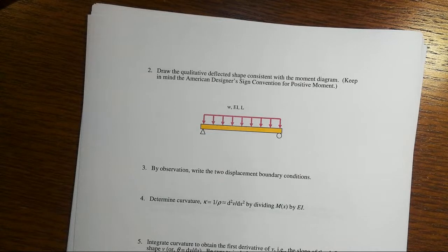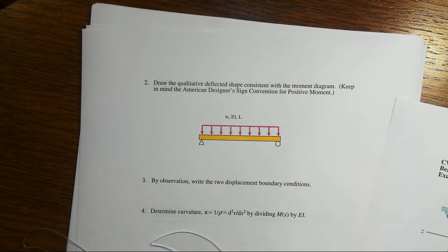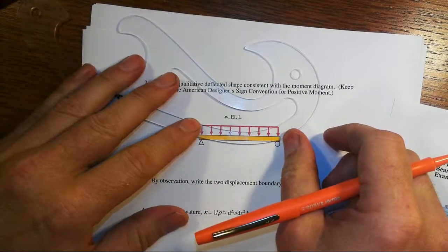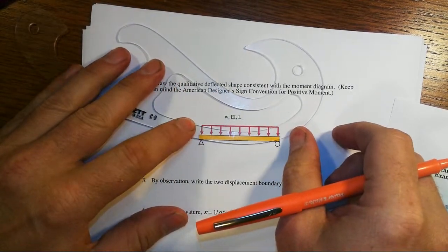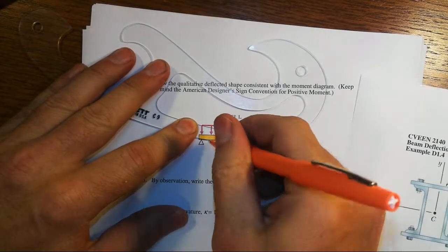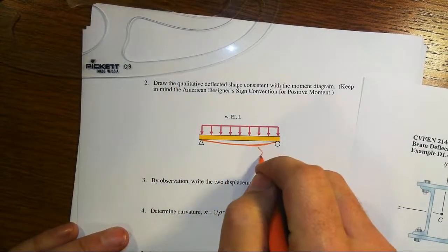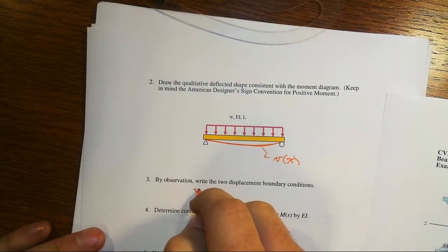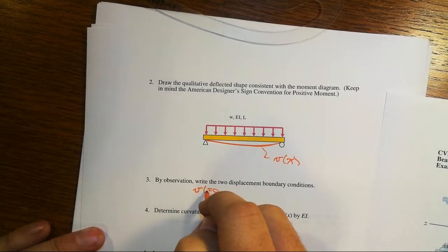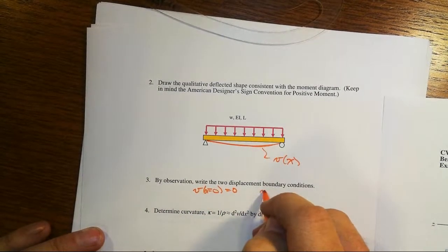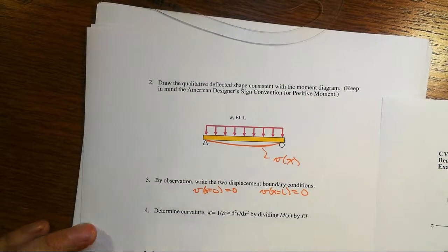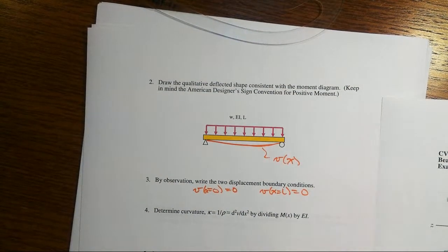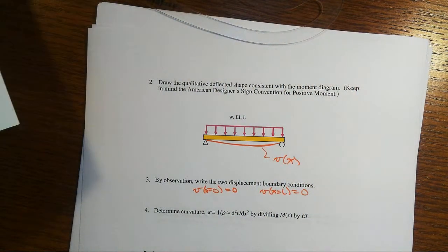And we know that that's entirely positive, and with the boundary conditions being what they are, with positive bending moment we've got positive curvature, or smiley face, everywhere. So this is easy to draw the elastic deflected shape. There's your little v of x. We've got v at x equal to 0 is equal to 0, and v at x equal to L is also equal to 0. Now, we're just going to turn the calculus crank down. It's just the same old thing over and over here.